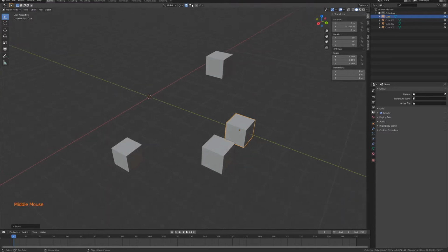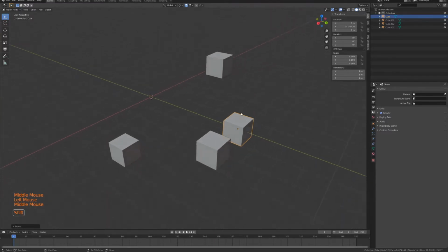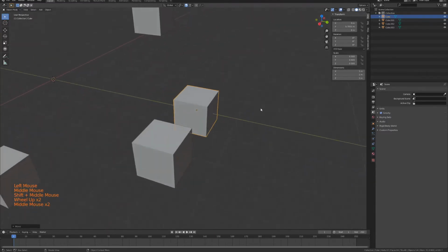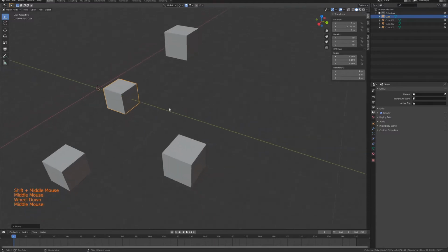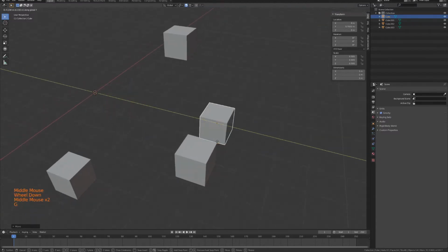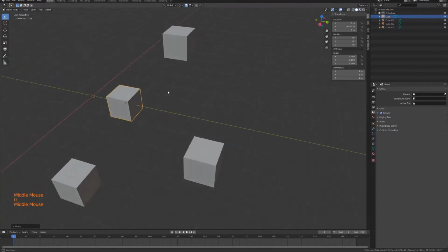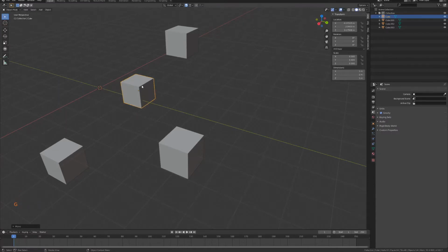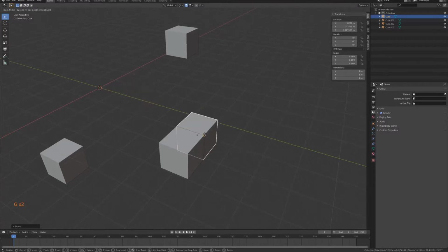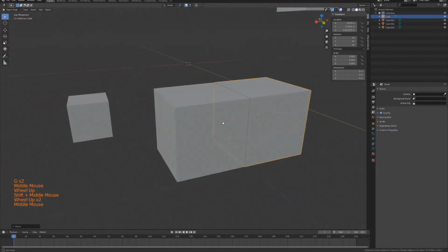So in this case, since the tool is set to closest, it will snap the closest point on this cube, which in this case is either of these 4 edges, and it will snap it to this particular point. Now, as you saw just now, if you don't constrain it, it will try and move the closest point, which is this vertex here, to the vertex that I highlight over. So if I do that, it will snap it very, very nicely.